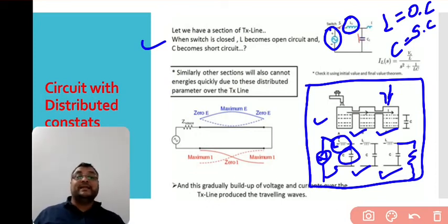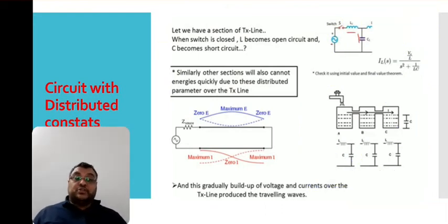During that, some of the wave is reflected back from that particular section, and this wave is known as a traveling wave, which increases the magnitude of voltage and may damage the equipment connected to the transmission line. So in this lecture we go through this basic discussion and understanding of traveling waves, and how the transmission line behaves when we switch on the supply.